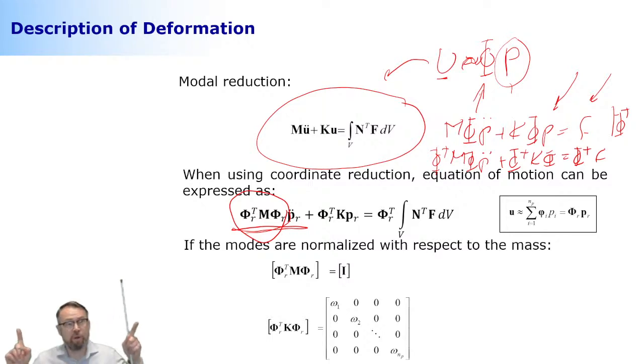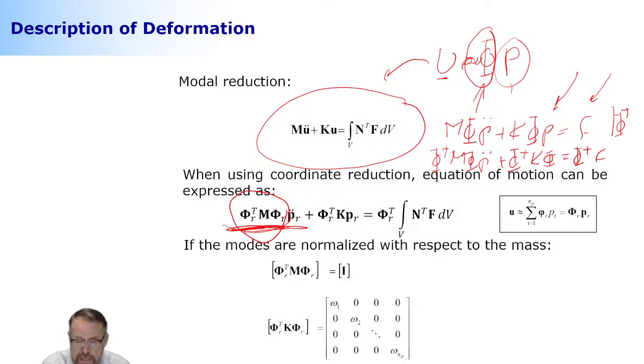And there's another, and this is where my professor at the time started to cry. There's another major consequence. If these deformation modes are orthogonal, as they are if they're coming from an eigenvalue analysis, then the off-diagonal components of this new matrix disappear. You get a diagonal representation, meaning that each of these modal coordinates can be solved independently. You can just take any modes you want and solve it without knowing anything at all about the others. And that's another beautiful consequence of this reduction technique.